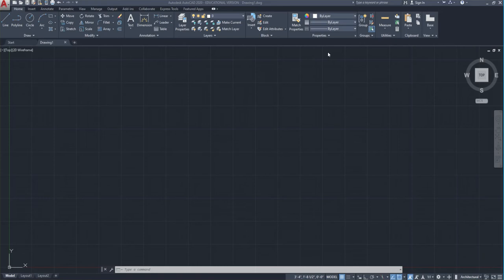Okay. So the first thing I want to talk about with regards to drawing site plans is the units we're going to draw them in. So we're going to introduce a third type of unit that is available in AutoCAD, and that is surveyor units, okay? If I come down here in my AutoCAD interface, where I just opened up a blank document, we're going to be working with a blank document today. If I just click on architectural, you see we have decimal, engineering, fractional, scientific. I don't have surveyor units down here, okay?